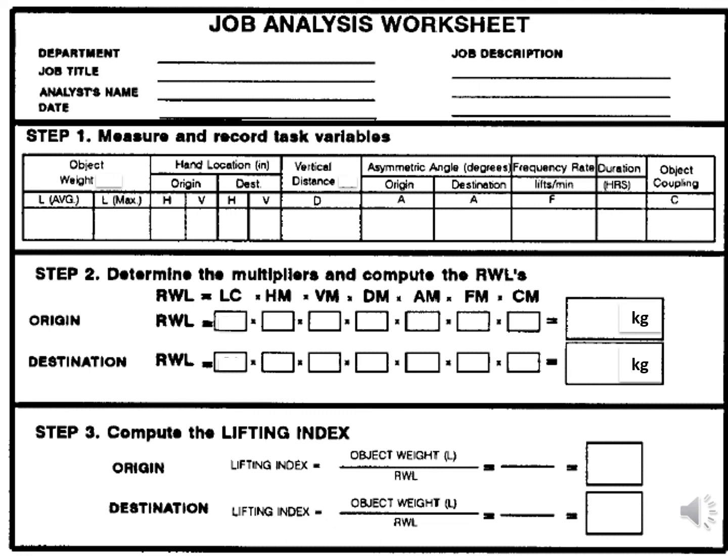Please pay attention that we first focus on the origin of the load, and after that the destination, the last position of the lifted load. Then we get the RWL for both origin and destination. After we obtain the RWL for origin and destination, we go to step 3 to compute the lifting index.